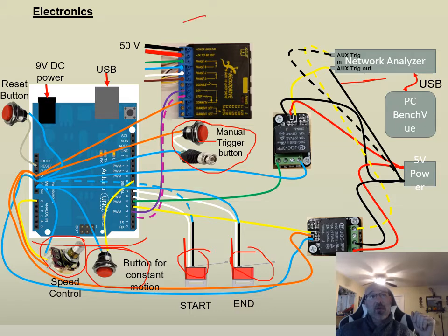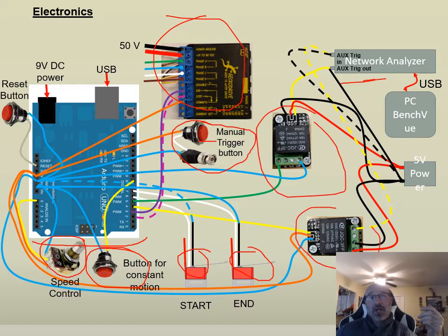So we have a motor controller here that we've introduced that we can send a step function to. And the way we've worked for this is now we've integrated this and tied it in with a couple of relays here from our network analyzer. So now it's a smart stepper system with a closed loop feedback in it. So as these antennas move forward to the new position, it will get a signal from our network analyzer saying, okay, send out our radar signal through the transmit antenna, receive it through the receive antenna, comes back up through our network analyzer program, realize, okay, yes, I've received it. Now I'm going to send out a TTL signal through our relay to go back to our Arduino board and say, okay, move to the next position.